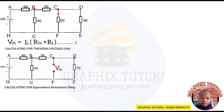If you look from point A to H, current will continue flowing from A to H to A, moving from the lower potential, the negative terminal, to the higher potential, the positive terminal, through A, through the 6 ohm resistor. So that current flowing in that manner is my I total, or we say my I1, that flows through this 6 ohm resistor from point A to point B. And we know that point B is a node.